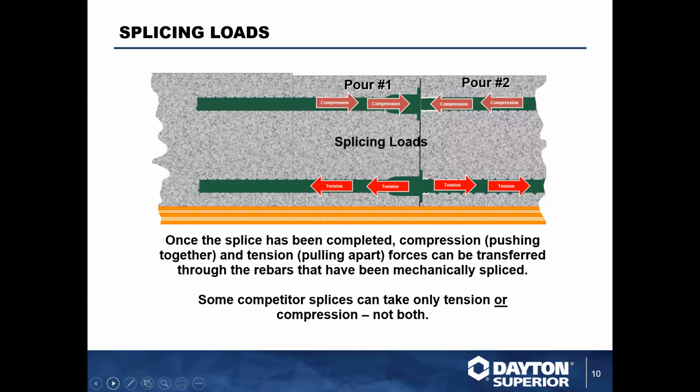And why are we doing this? Because, with splicing loads, you're looking at rebar. First of all, splicing is usually very good in compression. That means pushing the concrete together, you have to have that strength to hold up and keep the concrete slab in alignment. You also have to have the strength for when the concrete wants to expand and move outward. So you have to develop both compression and tension loads with your mechanical splice.